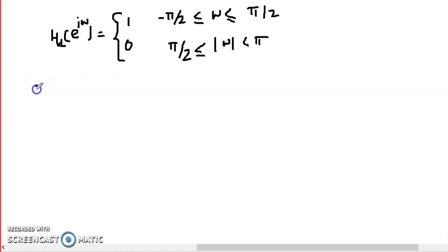So it is an ideal low pass filter, and we have to design this filter using the FIR method. FIR implementation means we have to determine h(n). Since it is finite length, we need to know how many terms to determine. Here it is telling us the number of terms is 11. So our aim is to design a finite impulse response digital filter which has this ideal response, and the number of terms will be 11.